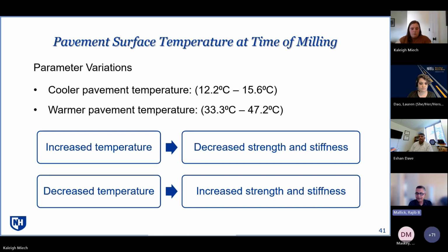But your question is very relevant. After we get the cores from the post-mill conditions and bring them back to the lab, what happens during that process? If it's a higher temperature, do we have a healing of the cracks? Do the cracks get reduced? We don't know. But as a matter of fact, you can say that if I do the milling at low temperature, you definitely create stresses that are going to affect your lower layers. I don't know whether that helps to answer your question or makes it more muddy, but I thought I would just share my thoughts. Thank you. That's good enough.